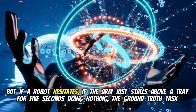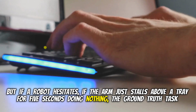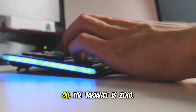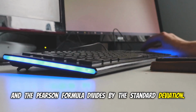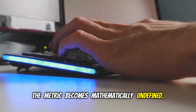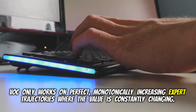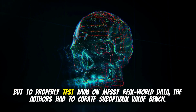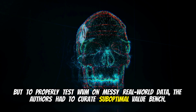But if a robot hesitates, if the arm just stalls above a tray for 5 seconds doing nothing, the ground truth task progress is invariant. It's a flat line. Oh, the variance is 0. Yeah. And the Pearson formula divides by the standard deviation, so you end up dividing by 0. Exactly. The metric becomes mathematically undefined. VOC only works on perfect, monotonically increasing expert trajectories where the value is constantly changing. Wow. But to properly test WVM on messy real-world data, the authors had to curate Suboptimal-Value-Bench.